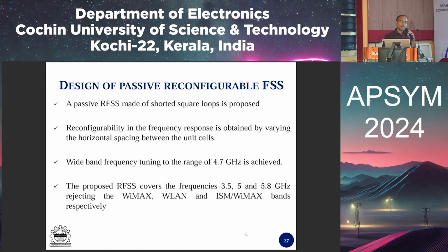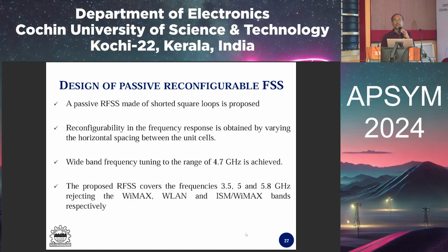So this is for a static response. Suppose you want to change the frequency, convert the FSS from static frequency response to dynamic, or say you want to change the response or shielding component, then we can go for passive reconfigurable surfaces or simply reconfigurable frequency surfaces. This can be active as well as passive. We tried our hands with passive, but we weren't into active because that involved more circuitry, which in turn adds complexity to the design. So we have tried out this passive reconfigurable FSS.